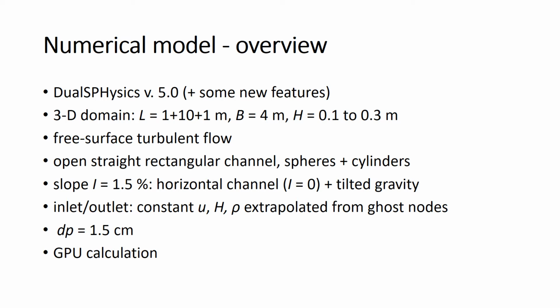Open boundary conditions were employed, imposing a constant inlet and outlet velocity of 0.5 meters per second and constant depths, while density was extrapolated from ghost nodes. The initial interparticle distance of 1.5 centimeters was selected. Simulations covered 50 seconds of physical time and were performed using a GPU.